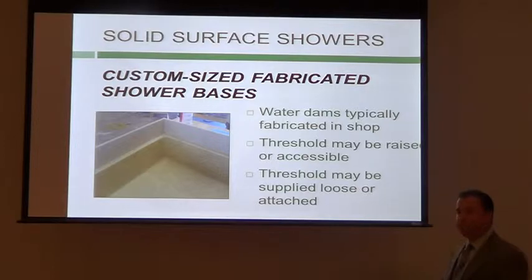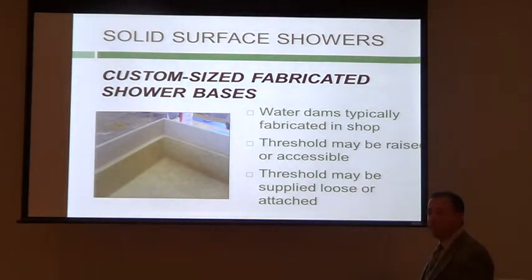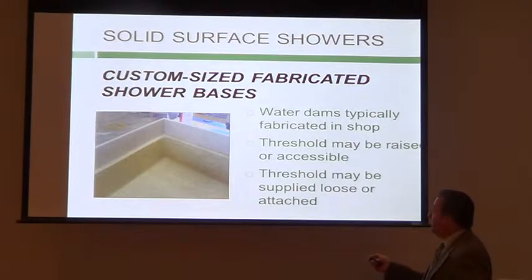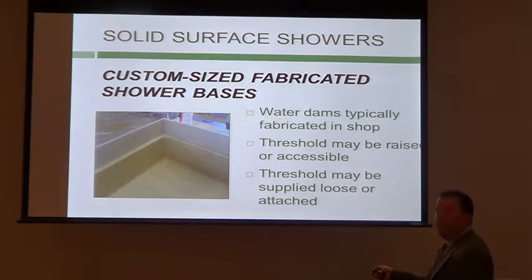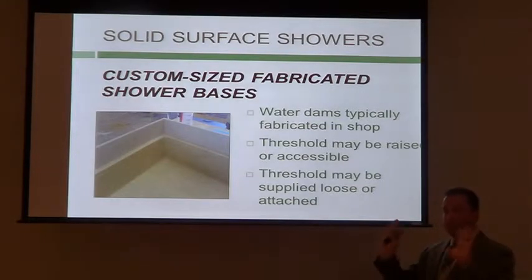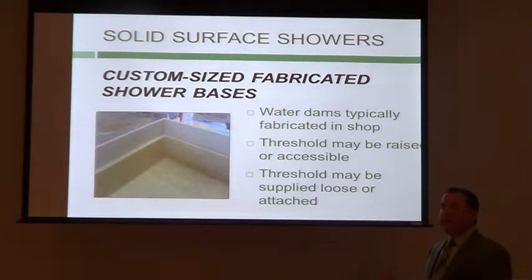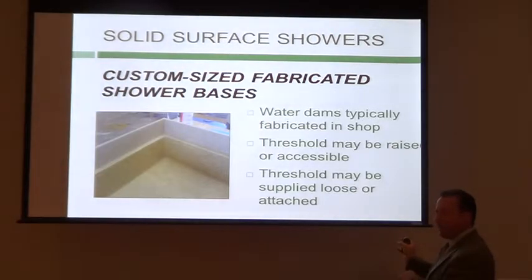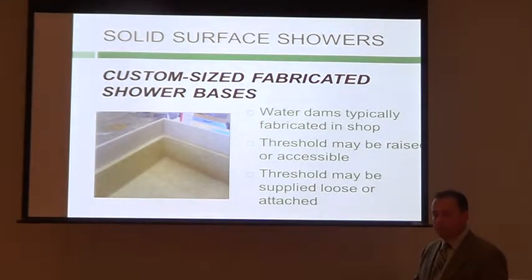And you typically take the shower wall panels over the front of that? Good question. In some designs, the panel will come all the way down to the floor. In my biased, preferred design, the panel comes up to the first step here, which gives you a nice level landing zone for your wall panel. If I take it all the way down to the floor, and this is coming up in a slide, we'll address it here real quick.